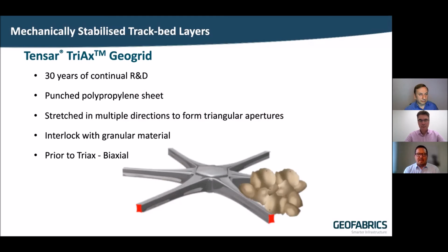So one thing to think about when you're considering a geogrid for this application is really how is that going to interact with that material? Are we going to gain the lateral constraint or lateral confinement that Erol had alluded to? We didn't hear much talk about tensile strength within Erol's presentation. It's some of the other properties: the thickness of the rib, the integral junction of the geogrid, and the stiffness of that geosynthetic plane that leads to the performance in a Tensar application.